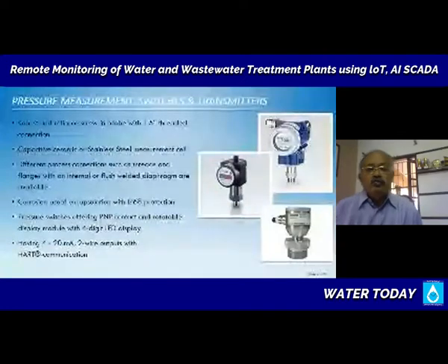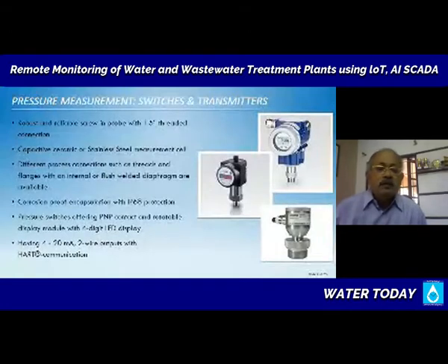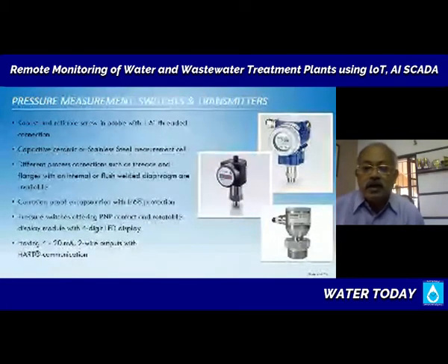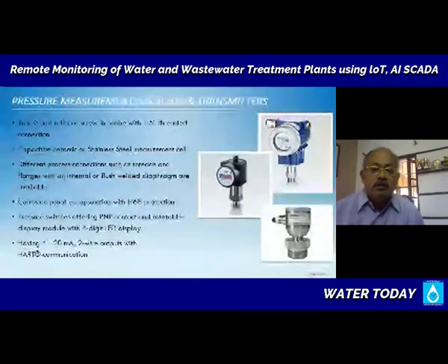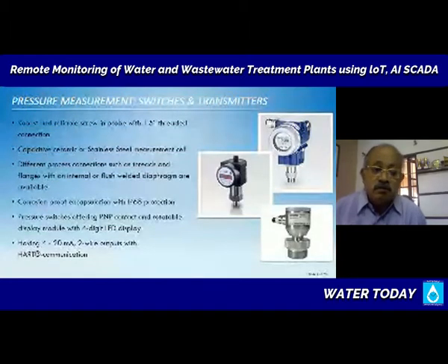If you use some odd type of signal which others do not support, then later if you want to make any upgrade or any change, you will be stuck because your measurement devices are in a non-standard category. So in any infrastructure upgrade, which is a serious subject in our country, standardization in terms of power supply, communication, the type of signal, and the type of enclosure you use is very important. So that's on pressure measurement.